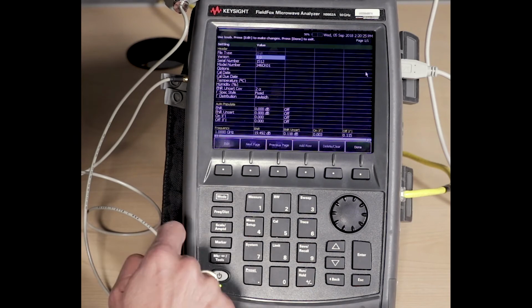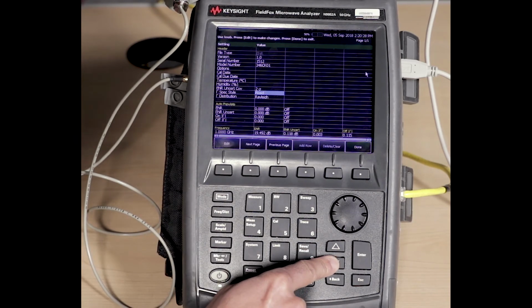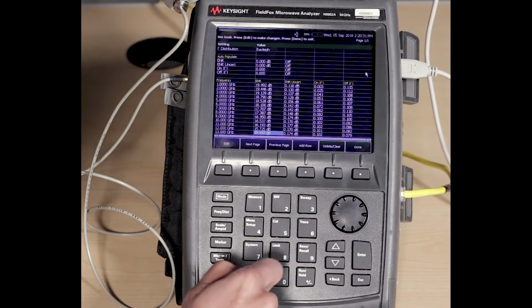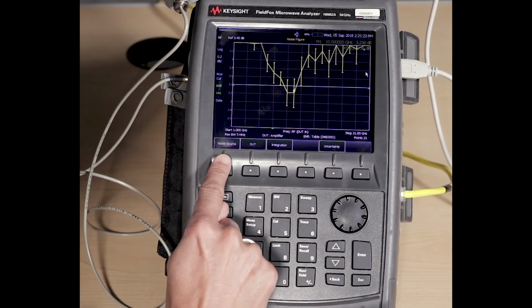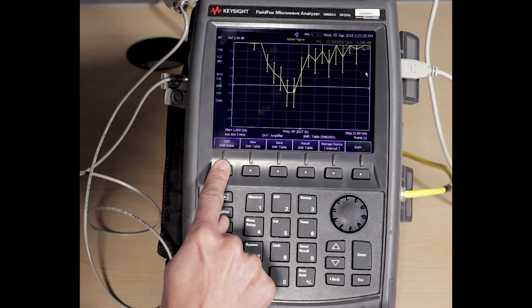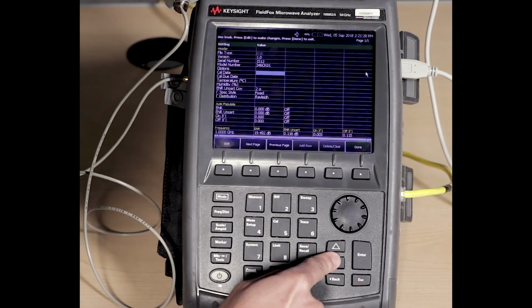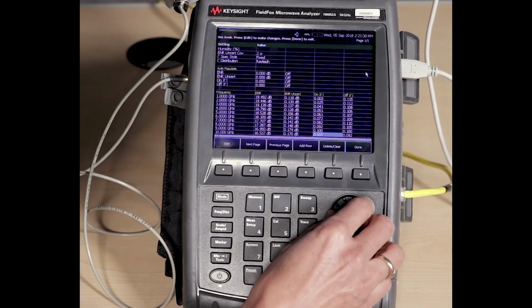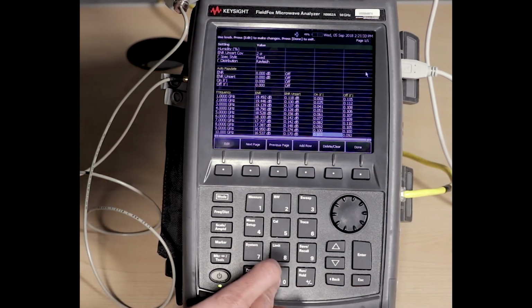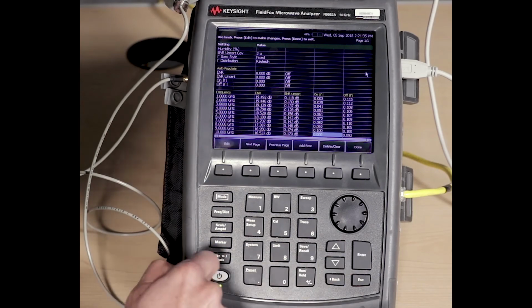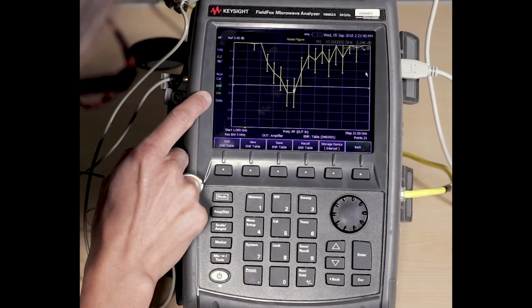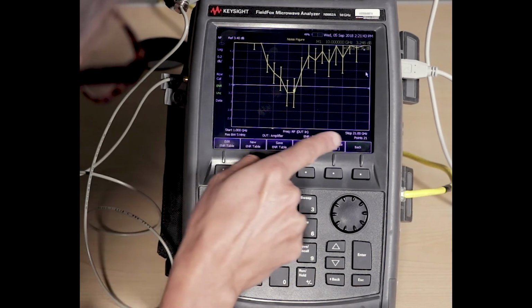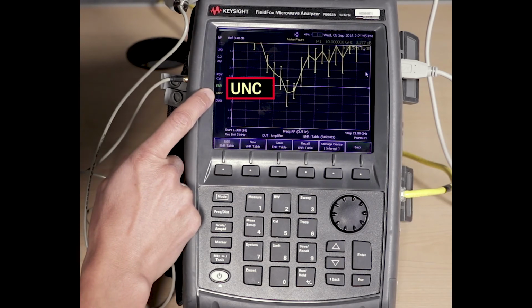And if you look at it, I said it was 2 sigma, fixed, Rayleigh, all those same parameters, and these are the values. I want to point out on the uncertainty that if you make a mistake, and let's come into the noise source, and you enter one of these gamma values, for example, a 0, meaning it's just perfect, which doesn't exist, I'm going to type in 0 at 10 gigahertz for the gamma. This uncertainty will turn into uncertainty question mark. It will do so once the sweep has caught up at 10 gigahertz, because it suspects you've done something wrong.